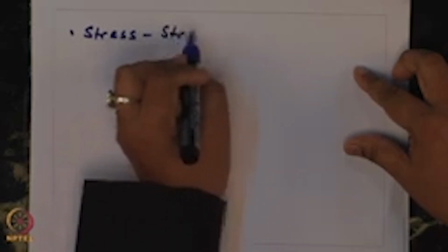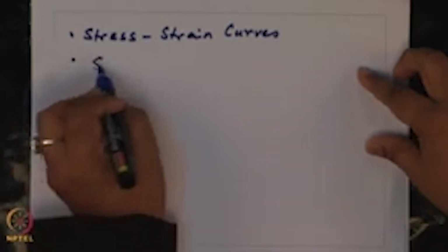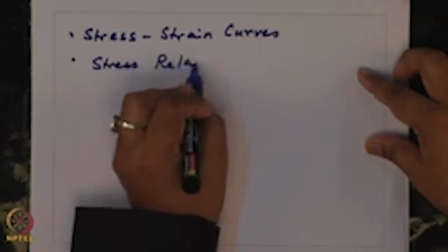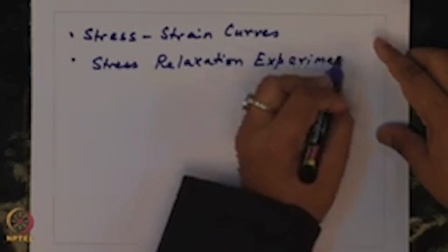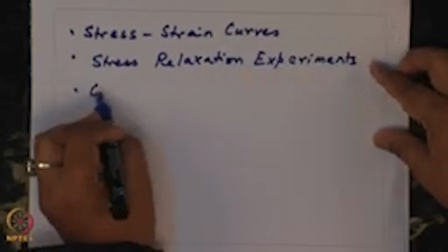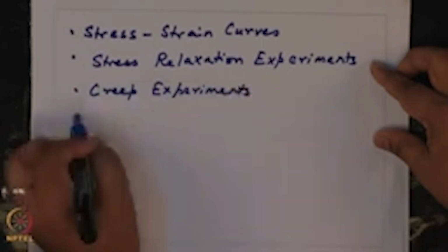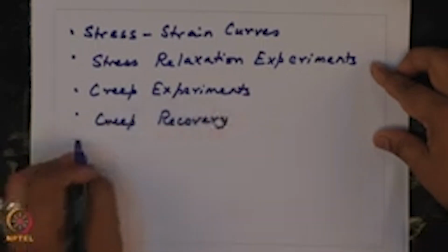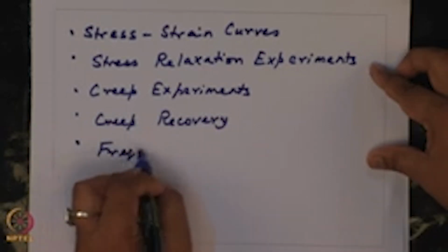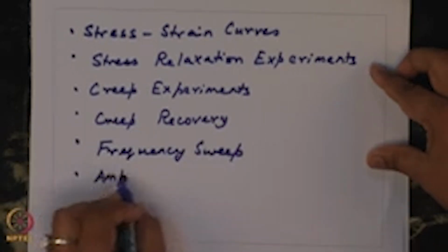You can do stress strain curves, stress relaxation experiments, creep experiments, creep recovery experiments, frequency sweep. You can also do something called amplitude sweep.